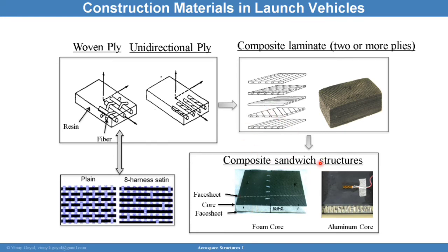Composite sandwich structures are quite beneficial for resisting buckling, and they're really good for rudders as an example. Rudder is one area where these are used. While the composite laminated approach could be used for the fuselage, for example, as the fuselage in this case only has to take, for the most part, in-plane shear loading, and the pressure differential across the skin of the aircraft as it ascends to space.